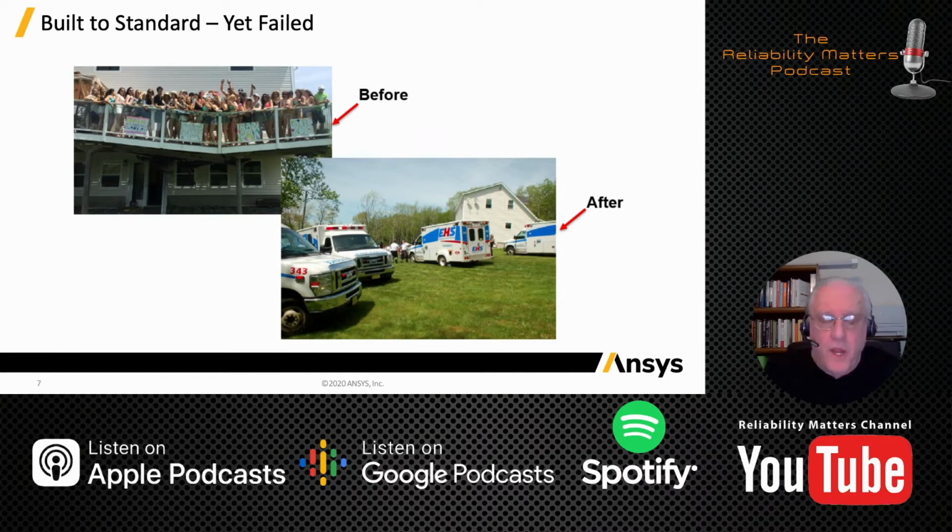They do not take into account dynamic loads, that is, people moving and dancing, nor do they take into account what's called reasonably foreseeable misuse. This is a legal term that we as design engineers are required to operate to, that we need to have our designs tailored not only towards the intended use, but also legally foreseeable misuse.